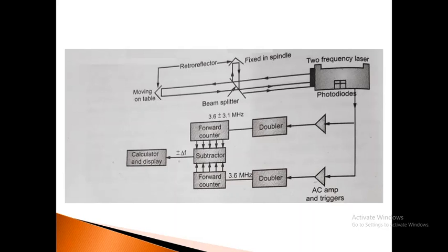As I was saying, the laser interferometer uses a helium neon laser beam split into two beams, each of different frequency and polarized. When the beams are recombined, any relative motion of the optics creates a Doppler shift in the frequency. This shift is then converted into a distance measurement.